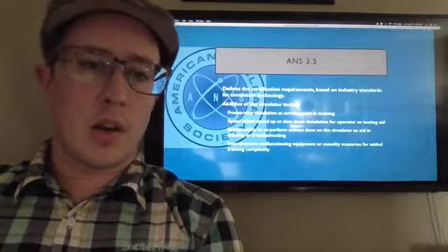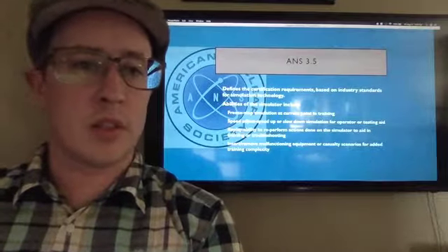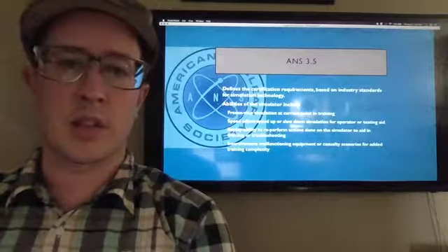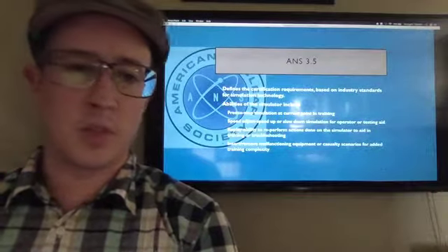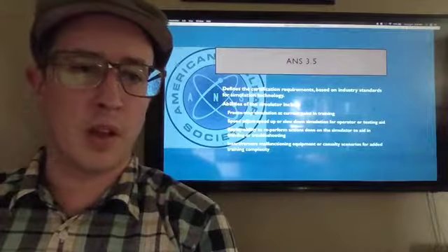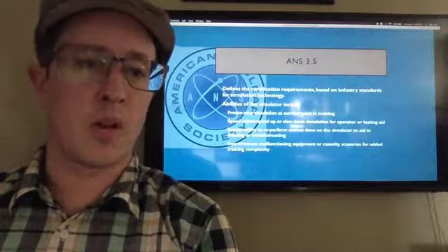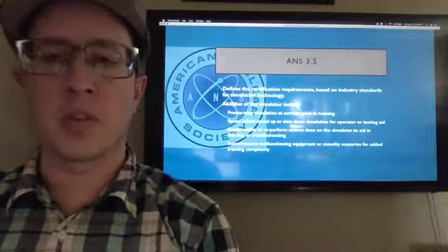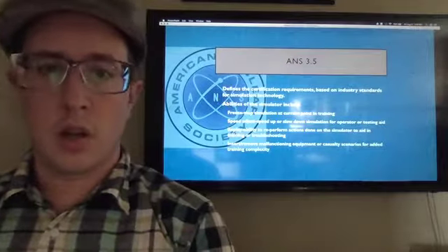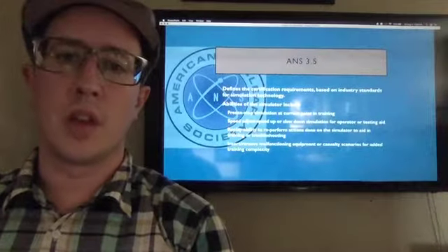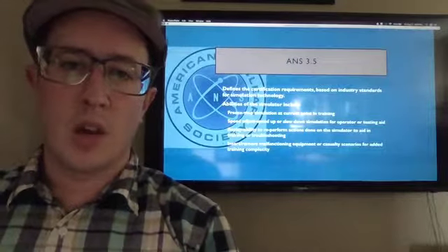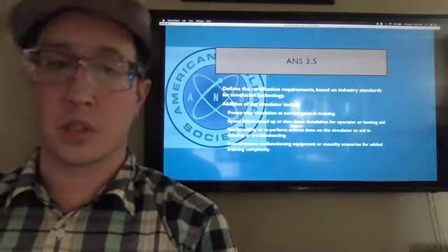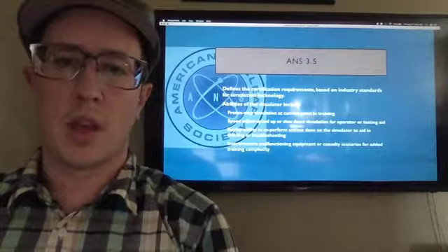They require some specific functionalities of the simulator that we have not yet talked about, and a couple I'd like to cover are freeze, speed adjustment, replay, and the ability to insert malfunctions, as we refer to them. First off, we'll discuss freeze, which is the ability for the staff instructor to stop the simulation at any given time. This is a beneficial tool that will allow the staff to potentially take a break and discuss an item with an operator.